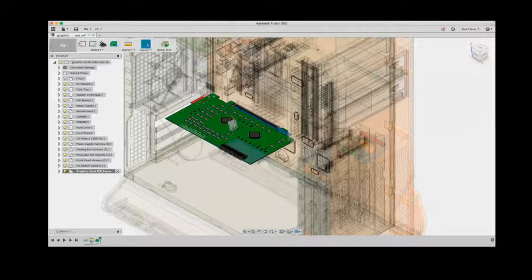You're on the Fusion side, right? Yep. I'm just going to pause it really quick, Paul. Yeah, so we're on the Fusion side. We're able to modify the board outline, and we're also able to move the parts. But those changes don't reflect the circuitry on the circuit board. So when that gets modified, it has to be pulled back into Eagle. That way we can make the modifications to accommodate what the mechanical engineer has done. Is that understood? Yeah. Go ahead.